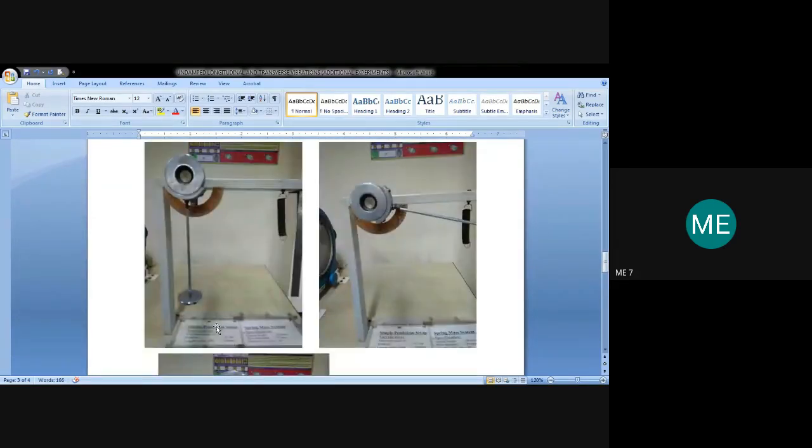What you need to do is attach the mass and then take your hand and bring it to some position. It's a graduated scale with 80, 90, 100 and so on. So pull it to some known value of displacement, which you call x1. Maybe you take it as 80 there and then leave the shaft. It will keep on vibrating. The moment it goes and then comes back, note down the final displacement immediately, not after 4 or 5 oscillations.